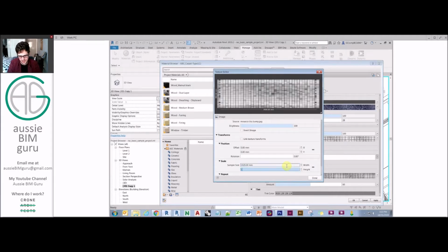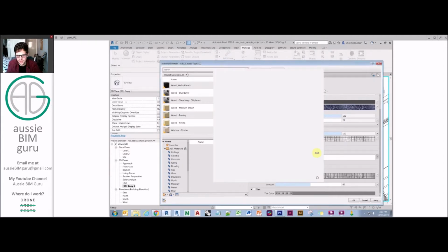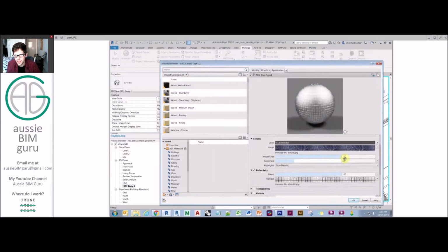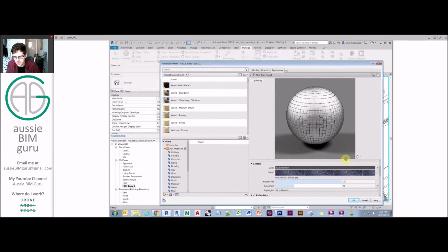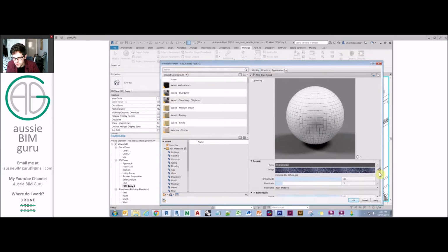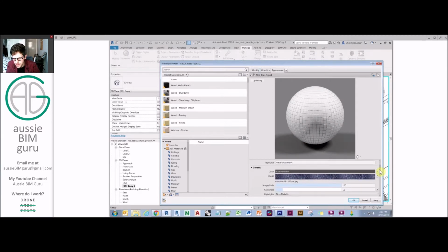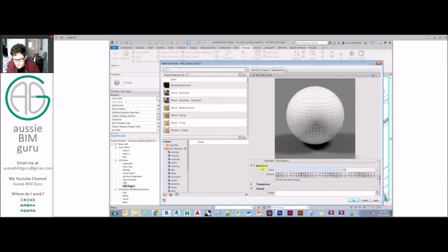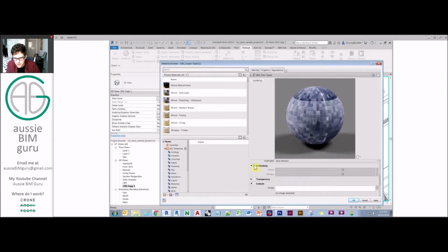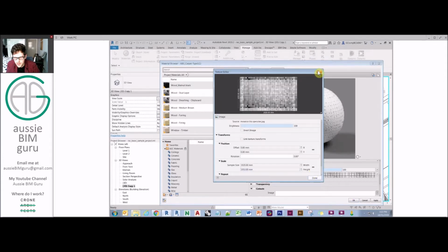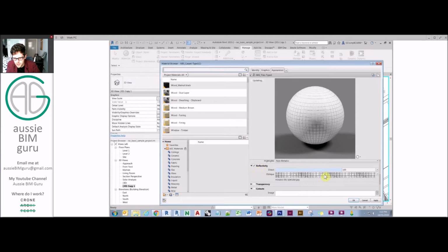Okay, 1920 by 1053. So now we should have a tile material that should look relatively solid. Obviously those reflections are almost taking the whole image out, which is quite surprising. So I think that reflection map is probably coming on a little bit too strong. Direct reflections 100%, that'll do it. So we'll just take that down to about 10% direct reflection.